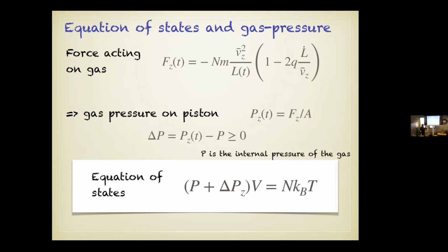So minus L dot times this is always positive. That's why this term gives you a positive contribution to work whenever you push in or push out, while the other part becomes reversible. And this is the case that the piston is at a higher pressure than the internal pressure of the gas while pushing in. This is something that engineers know. That's well known. And I think I'm almost through.